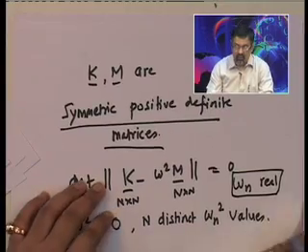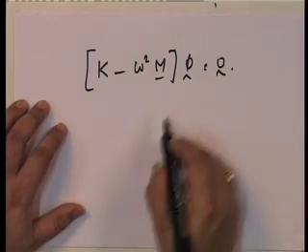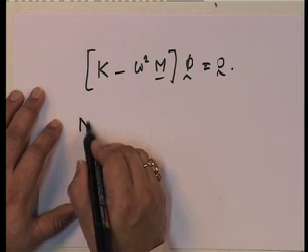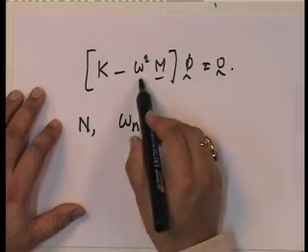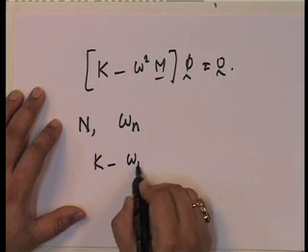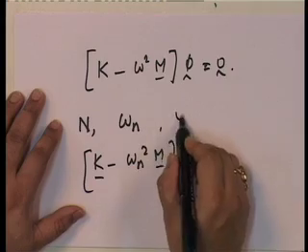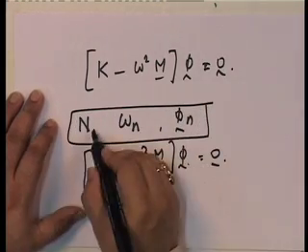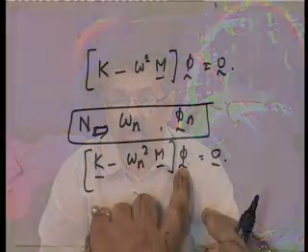So, that means what we get finally is the following: by solving this eigenvalue problem, this eigenvalue problem is solvable for n omega n values, okay, and for a specific value of omega n, you find out phi n. So, every omega n has its own corresponding phi n, and there are n such omega n and phi n. Now, this omega n squared are known as eigenvalues, and these are known as eigenvectors.